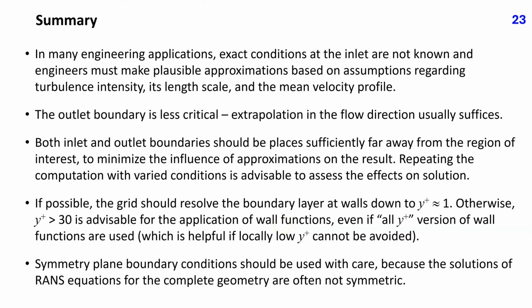The outlet boundary is less critical. Extrapolation in the flow direction usually suffices. Both inlet and outlet boundaries should be placed sufficiently far away from the region of interest to minimize the influence of approximations made in boundary conditions on the result. Repeating the computation with varied conditions is advisable to assess the effect of variations on solutions.